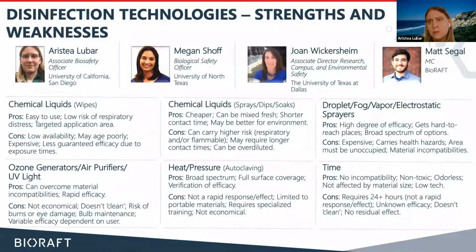So the decision that was made on our end was actually more that I think they changed the MERV rating on some of the filters. At least most of the buildings that had been built recently enough in which you could change the type of filter with a different MERV rating, those changes were made, but we did not decide to add additional UV to our air handlers. I was actually a little bit surprised that ASHRAE made that recommendation.